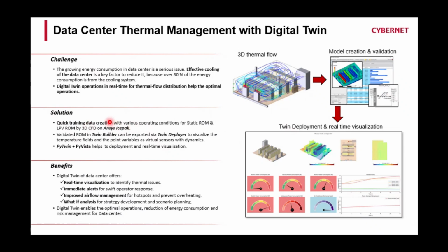First of all, you build this training data, using Ansys Icepak in this case for the data center simulations. You simulate many different kinds of scenarios to convert into the ROM. We have two: one is static, for the flow field and the temperature profile across the room, and then for the transient one, in a data point, is the LPV ROM. Once you have all these, you validate them inside the Ansys Twin Builder, and then eventually you deploy together with PyVista for you to visualize however you want.